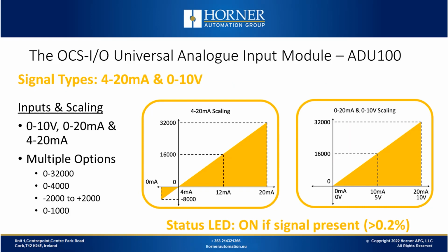Now we'll look at the readings that come back and what format they're in. Remember, we're doing analog to digital conversion, so we'll get a digital value back into our analog input register, and we can choose how we want that data to come back. With the highest resolution, we can choose 0 to 32,000 counts. If we want readings that are easy to deal with, we can do 0 to 1000 as the range coming back, but resolution will be lost in exchange for what will probably end up being extremely stable signals.